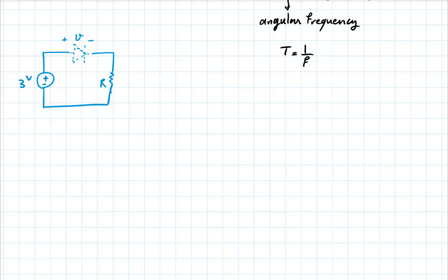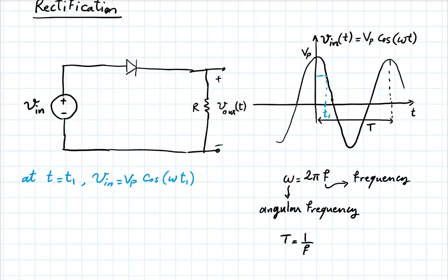And so with a simple analysis like that, we saw that if you applied a positive input to this, so if you were anywhere in this range of time, where the input is positive, the diode would simply be on, conducting current in the forward direction, and not taking up any voltage drop, right?